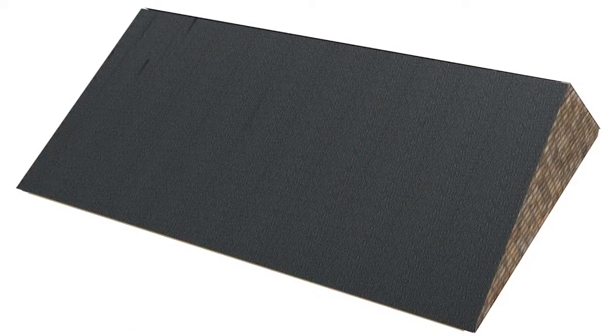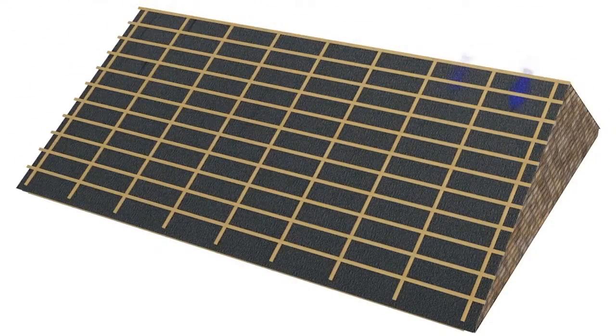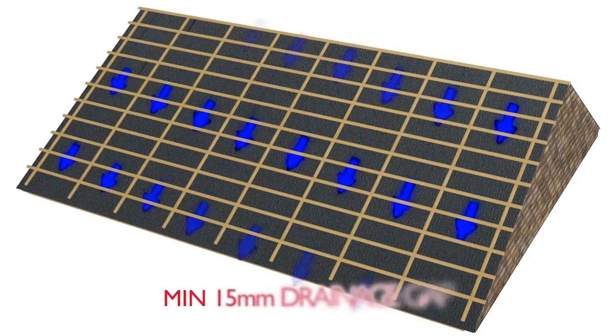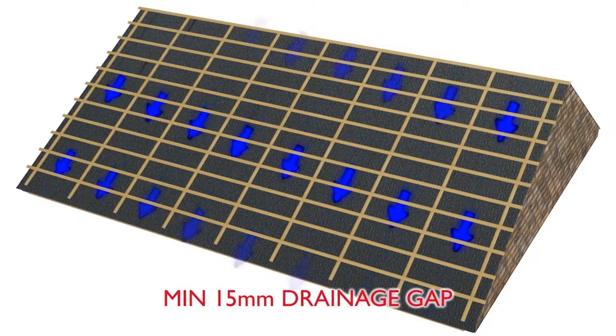It's also important with this configuration of roof that any moisture passing through the outer waterproofing layers can drain properly. This may occur where there is damage to slates or tiles, or where wind-blown rain passes up under the outer covering. If slates or tiles on battens are used on the roof, there must be a gap under the battens in order to ensure this drainage.